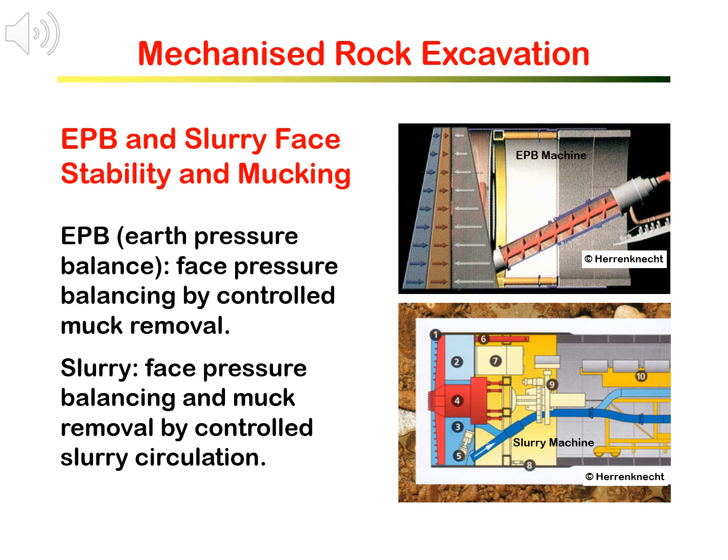As shown by the upper figure, in EPB mode, the earth pressure in the chamber is controlled by the muck removal rate through the screw conveyor. Earth pressure can build up if the muck in the chamber is removed less than the muck being excavated and then coming into the chamber.